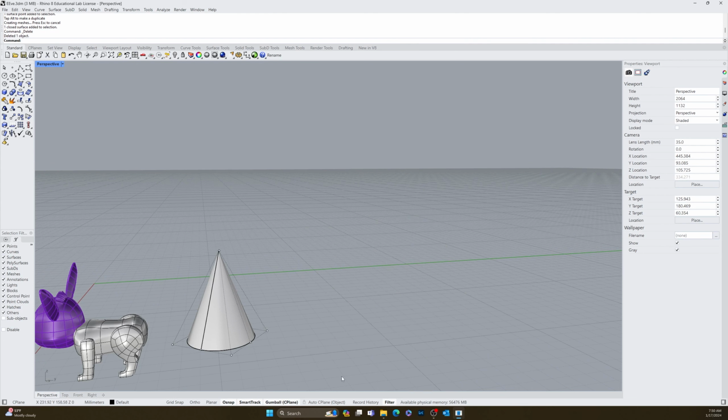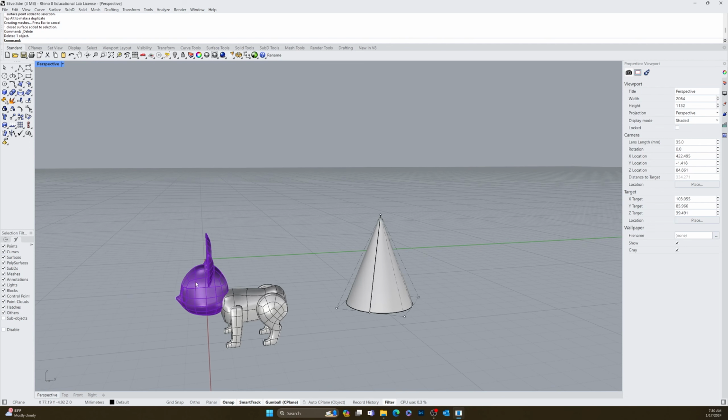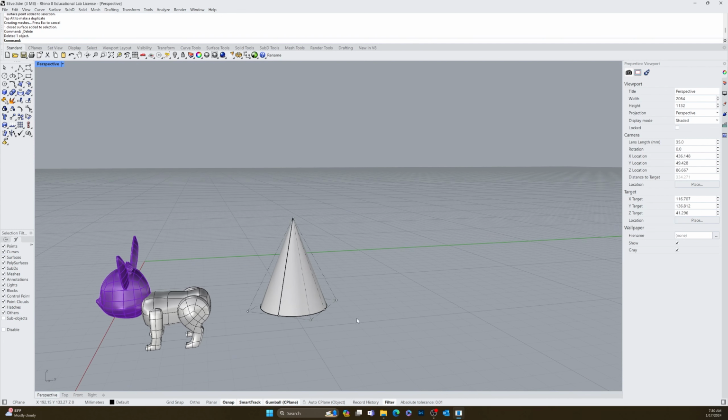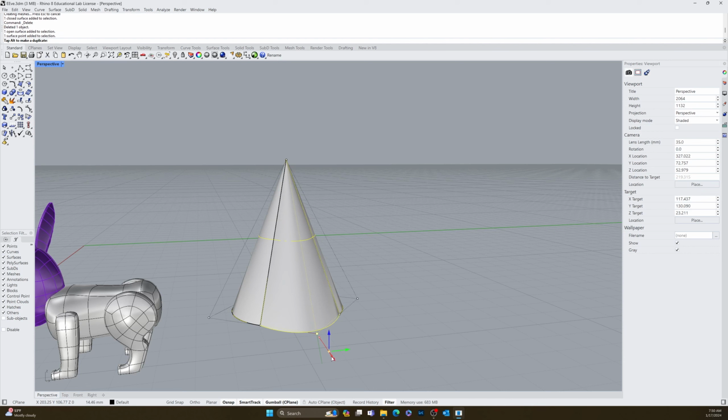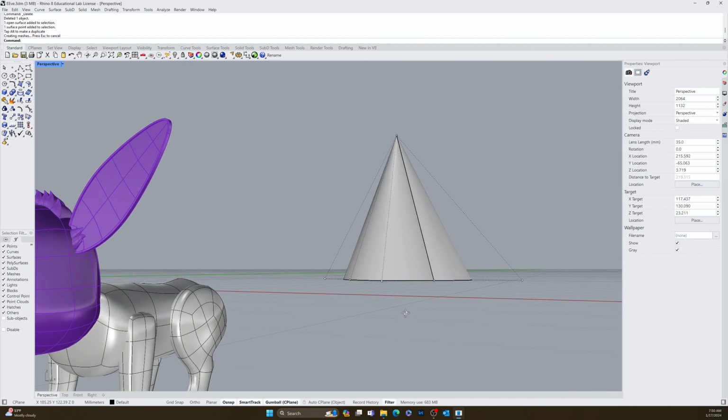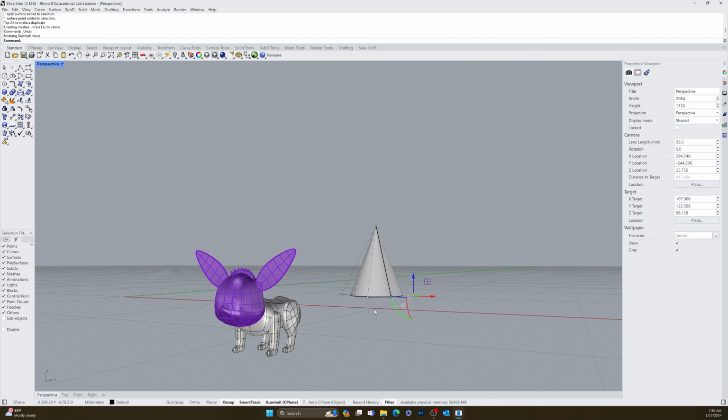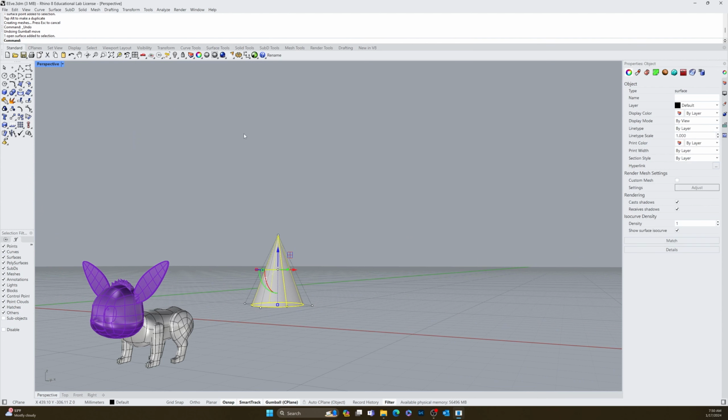So that we could have also used to make the face here, no problem. But the problem that I've got with this right now is actually the quantity of control points doesn't allow me to control it the way I want it to. So I'm going to go ahead and isolate this. My standard tab here, go up to the light box here again and isolate.